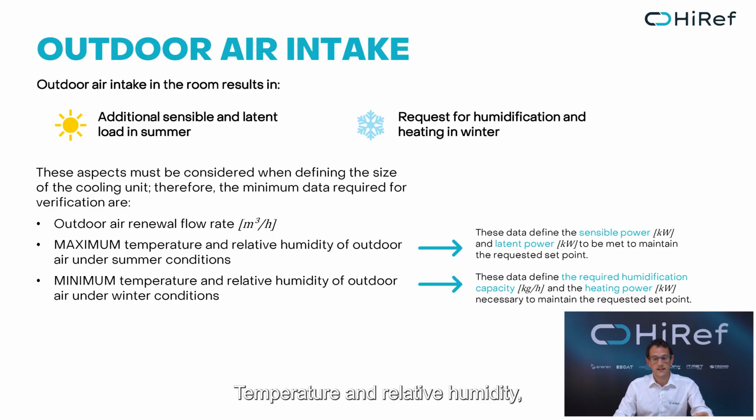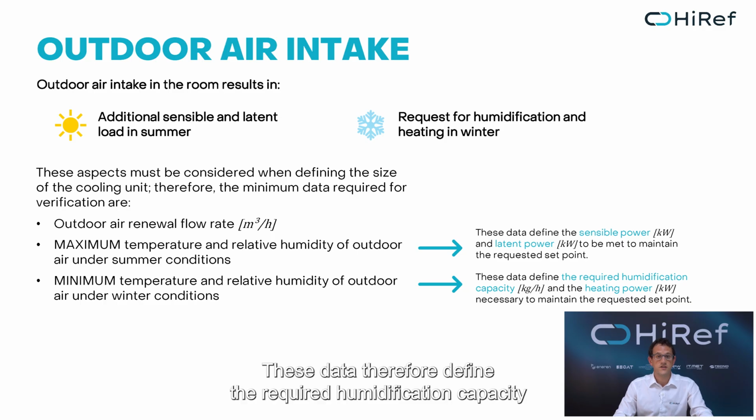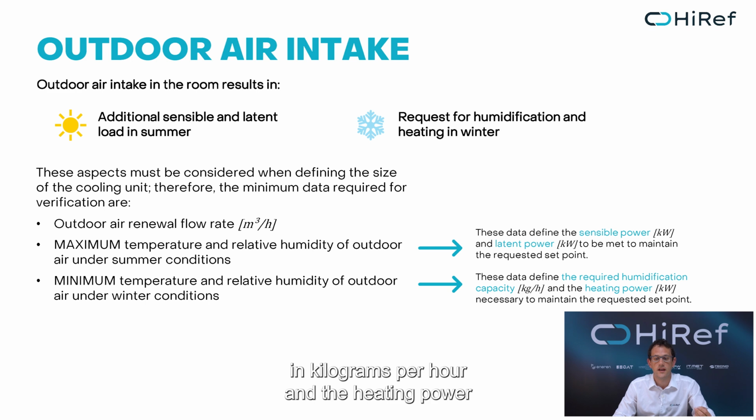Temperature and relative humidity, minimum values of outdoor air under winter conditions. These data therefore define the required humidification capacity in kilograms per hour and the heating power in kilowatts needed to maintain the required set point.